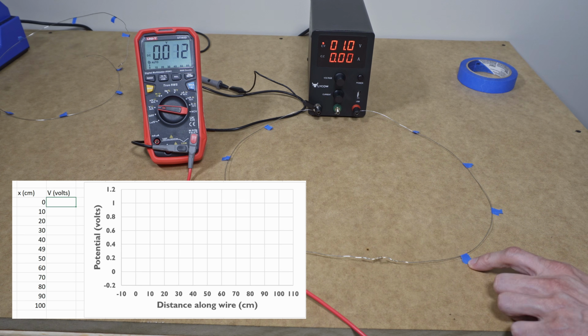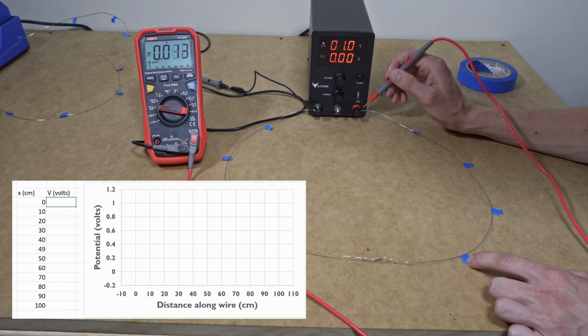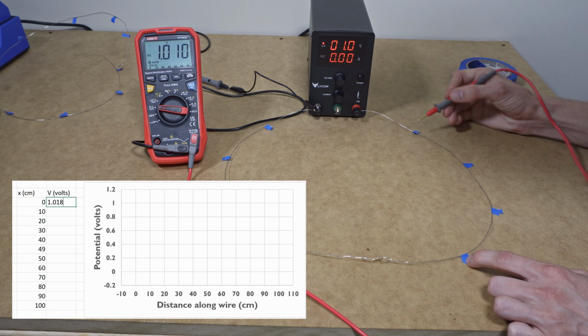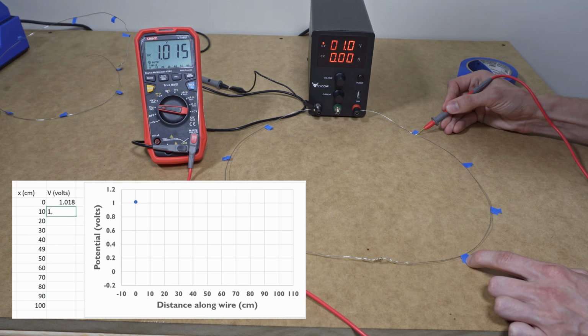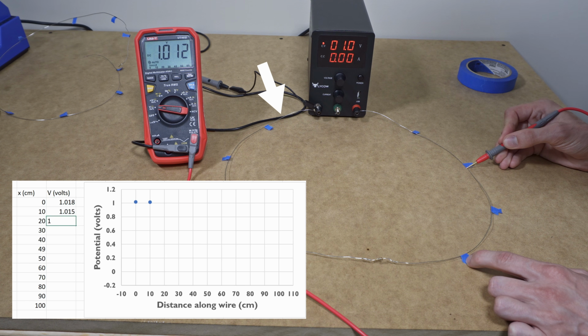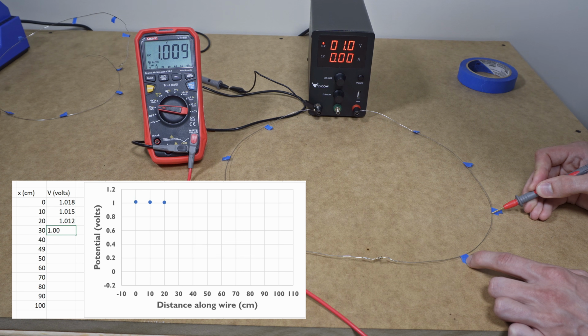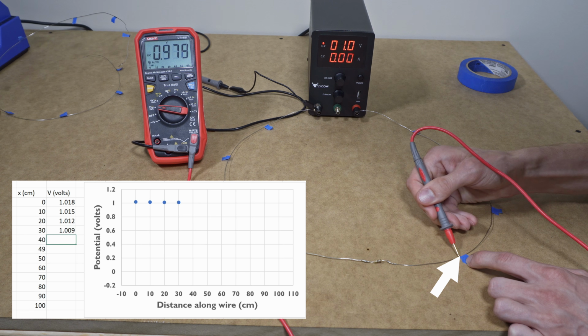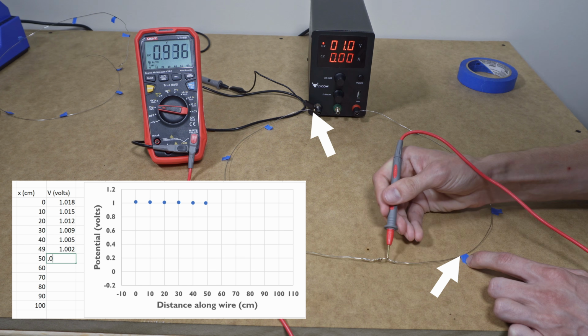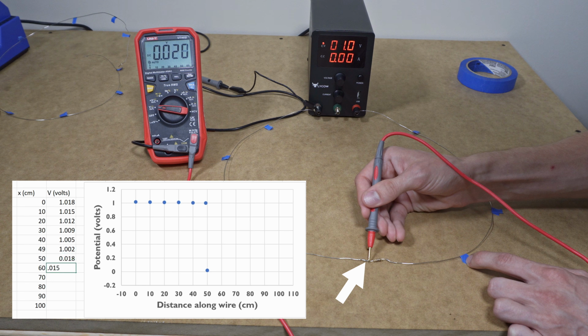It's also important to keep in mind that voltages are always relative in circuits, and the water model is no different. In the intro example, I had the negative clip of the multimeter attached to one side of the power supply for every measurement. A voltmeter like this only measures the difference in voltage between two leads. So when I say this point is at 1 volt, I really mean the potential at this point is 1 volt higher than the potential at this point. And when I say the potential here is about 0 volts, I really mean that this point and this point are at approximately the same potential.